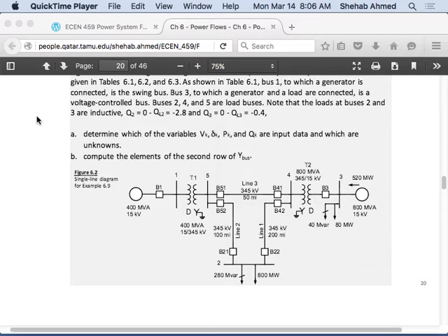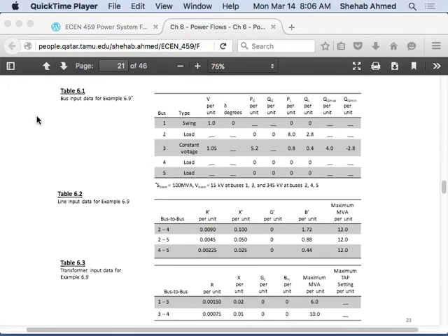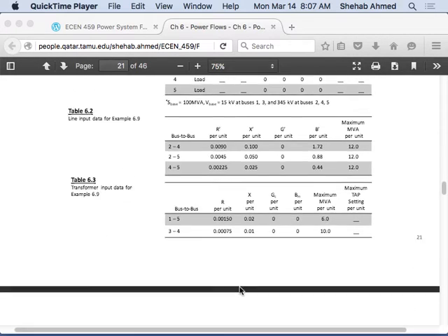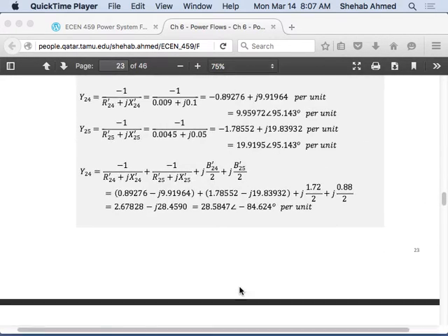And then today we will, and of course, to fill up the admittance matrix, we need all the data of the various components. So the line data, the transformer data, all of that we had to plug into the admittance matrix, right? So this is how we set up the problem and constructed the admittance matrix, but we don't know how to solve the power flow problem yet, right? We sort of have an idea of what we need to do, but we didn't do that yet. So let's see what we will do.